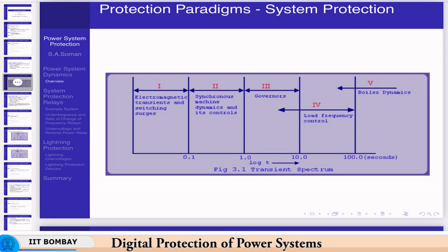the synchronous generators will begin to react, because they don't react instantaneously, because they have a high inertia. If you remember, 2H by omega s d2 delta by dt2 is equal to Pm minus P. So that H, the synchronous machine inertia, is quite large and it takes time to react. Because it takes a longer time, the frequency will be lower than the electromagnetic transient frequency. So this is the time period shown by 2, that is about 100 milliseconds